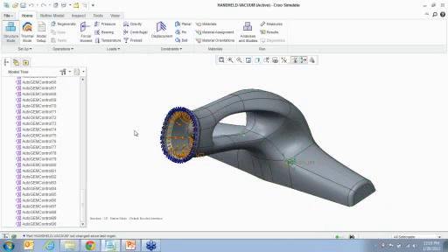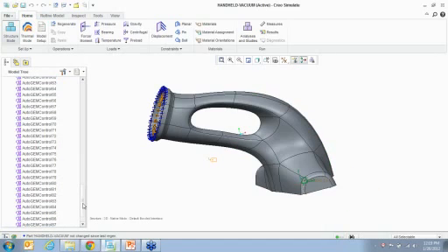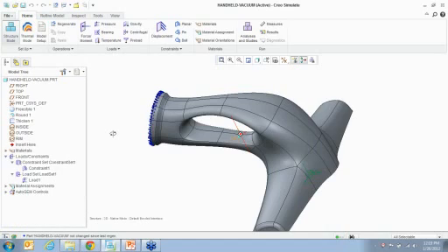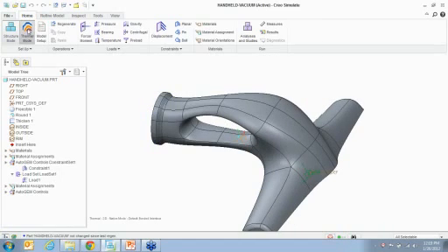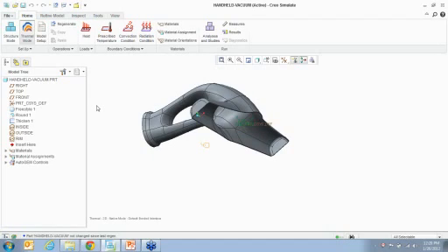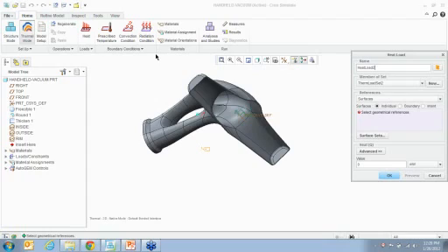Now real quick, we can also go into a thermal mode in it. You can just switch back and forth, thermal mode or regular mode, and say I want to go ahead and add some heat load. Say I want to put a heat load right here, and then say the heat over there is, say, 300.